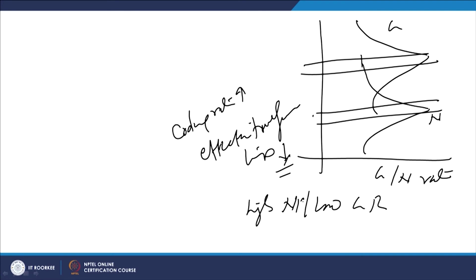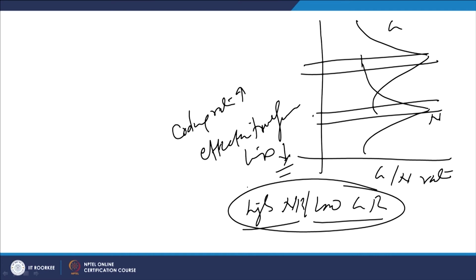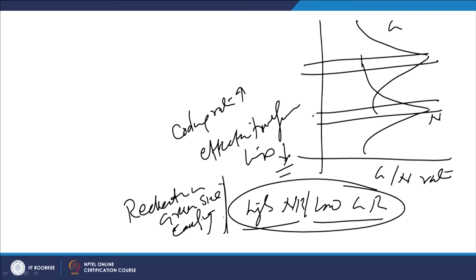So, because of the high nucleation rate and low growth rate, we find that there are a large number of nucleants and the growth occurs up to a limited extent, and a combination of these factors leads to the reduction in grain size of the coating.